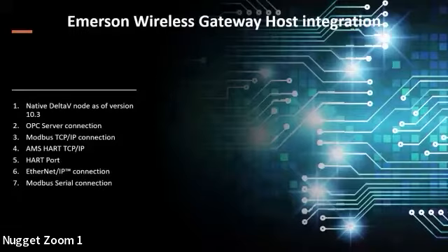You can also, via the gateway, bring it in OPC, Modbus RTU, Ethernet IP. So many ways of getting that wireless data from our devices to the gateway and then from the gateway into your system. Very easy to actually do. My expertise is actually on the wireless end of it, not necessarily hooking up from there. That's where Caltrol would come in and they'd help set that up if necessary.